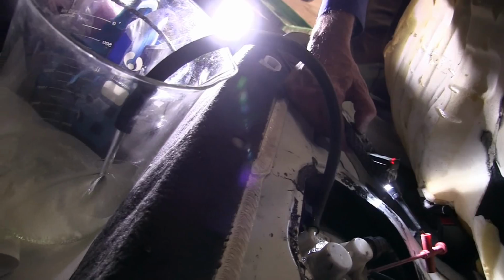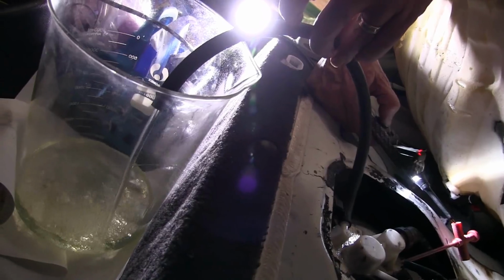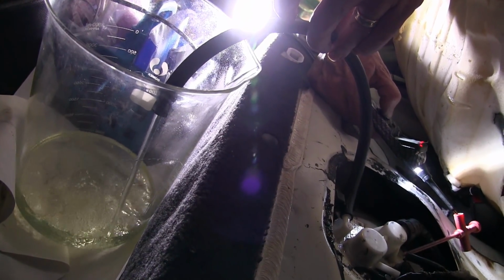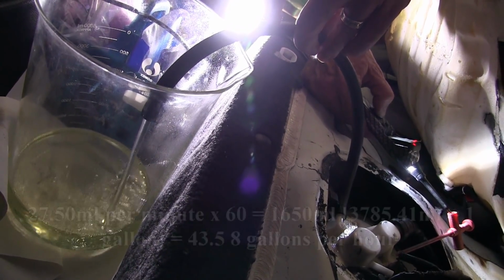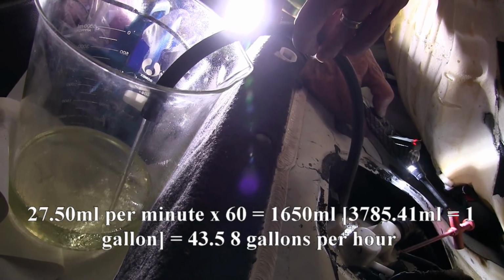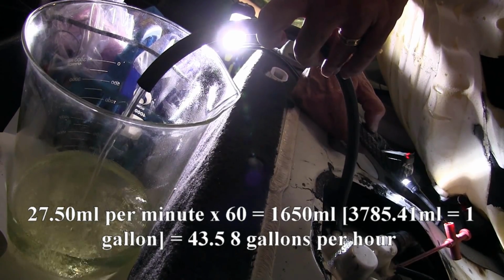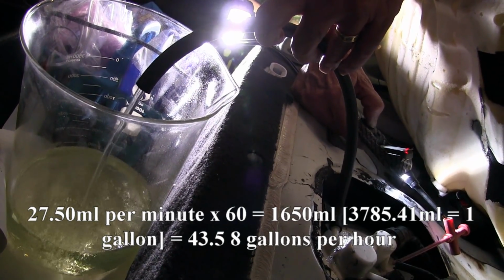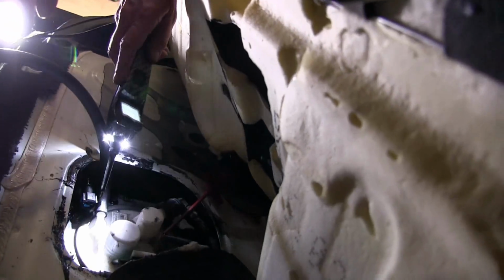So we're flowing gasoline. Now I've already timed this, and I get 2,750 milliliters in 1 minute. When you do the math, that's about 43 gallons in an hour. That's more than enough to run this little engine. So as you can see, I have a really good flow. Now what I want to do is put this line back on here, and we're going to go test it up at the engine. So let's go ahead and do that.